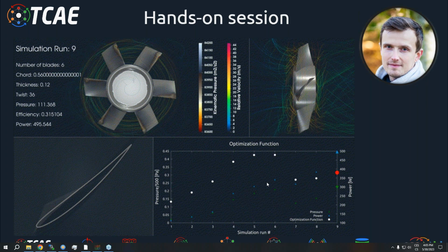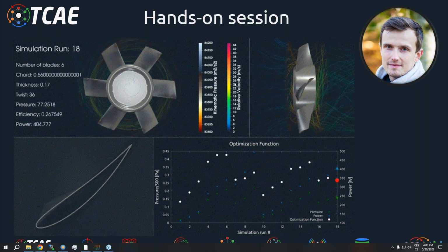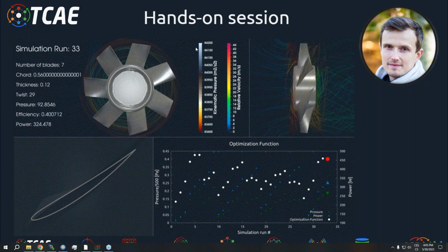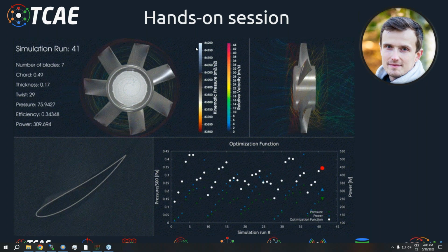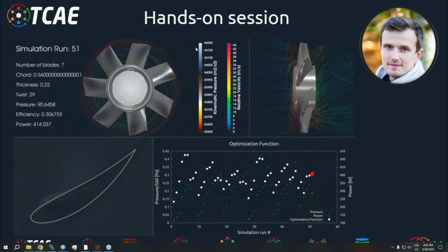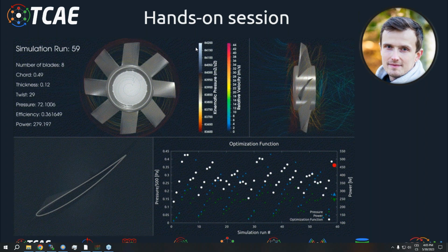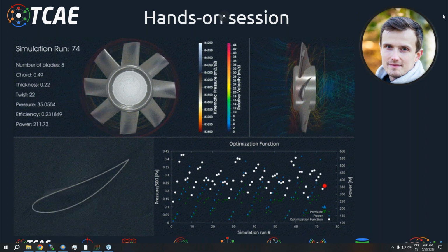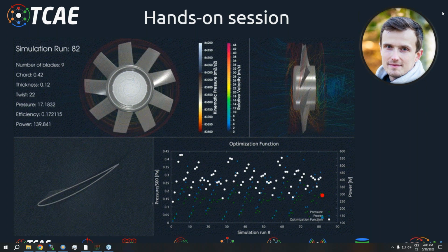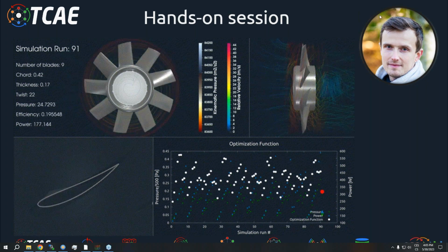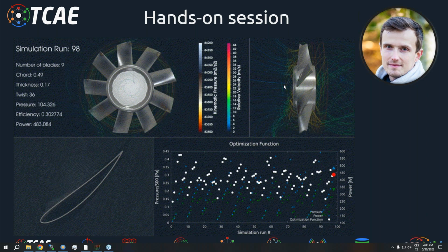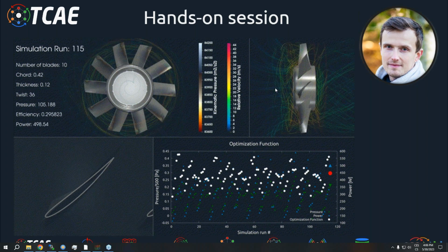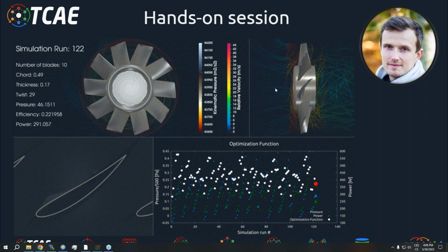You will create a copy of it, so you will save the project as a new one. You will preset new meshing, and base, for example, you will set the TOP as a DOE and pick up, I don't know, 10 combinations from the parametric space you did. It's best design, some designs close to it, some designs far from it, and run it again to see if you still get the best design of the previous optimization.